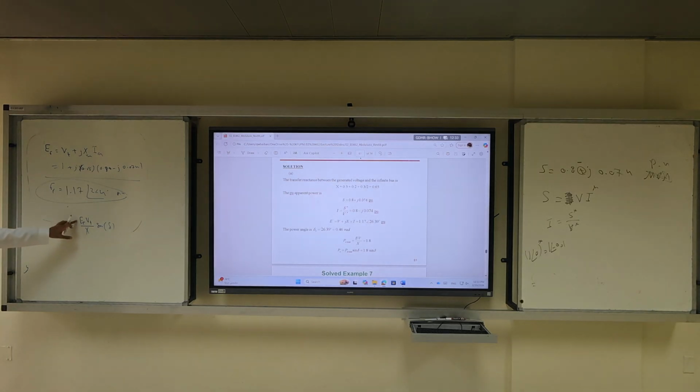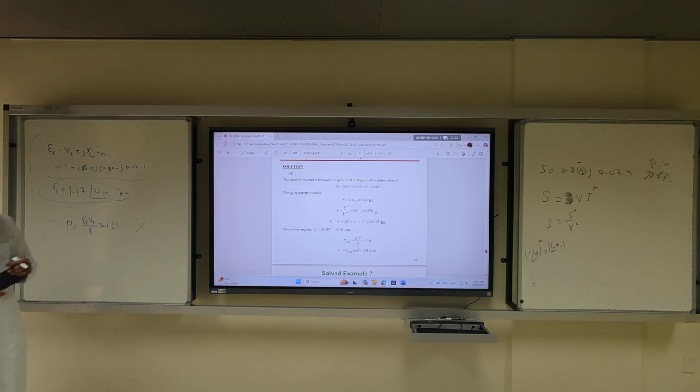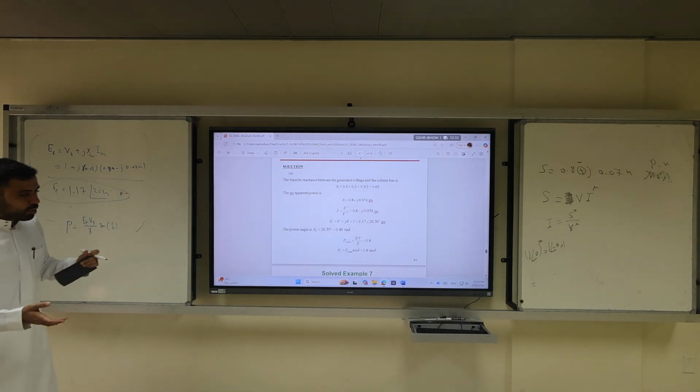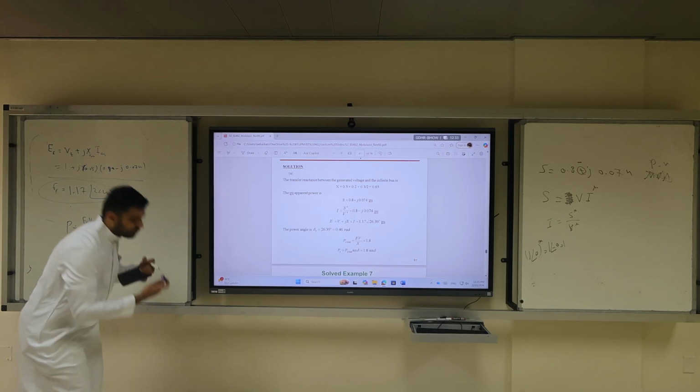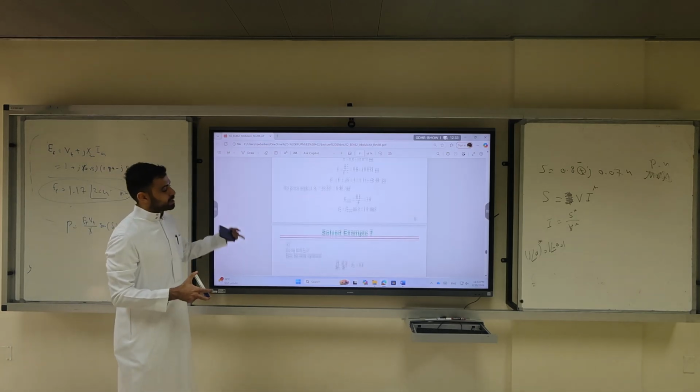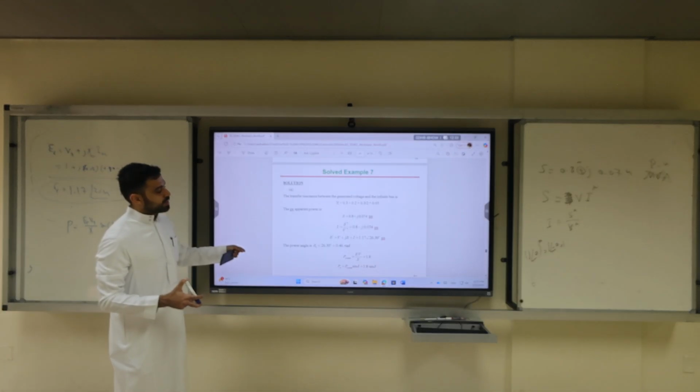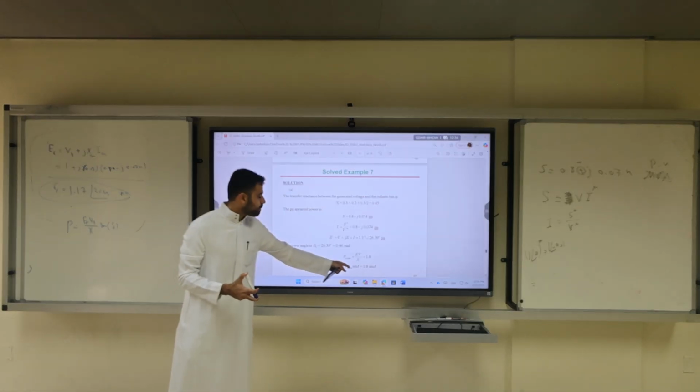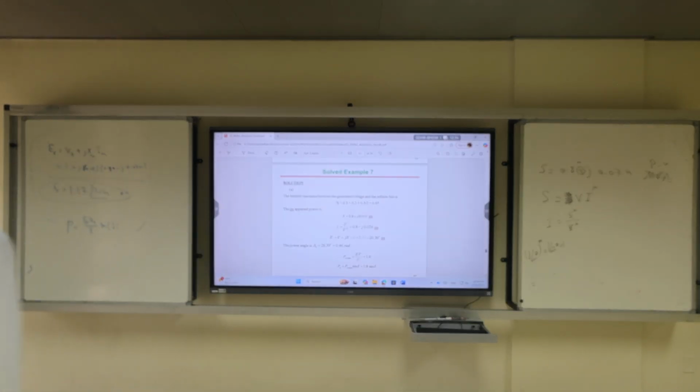So that's the equation. You have EF, you have VT, you have X, you have sine delta, which is 1.8 times sine delta. That's the power. You can substitute. What's the maximum power? Put sine 90. What's the power right now?